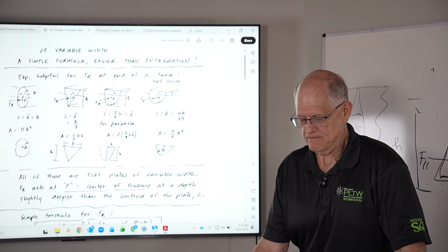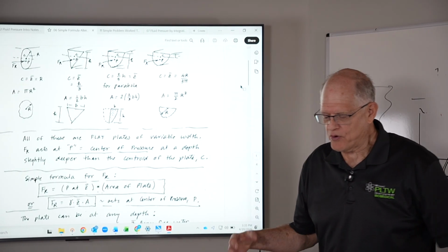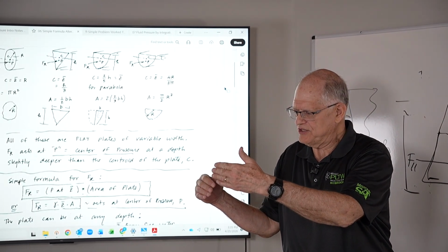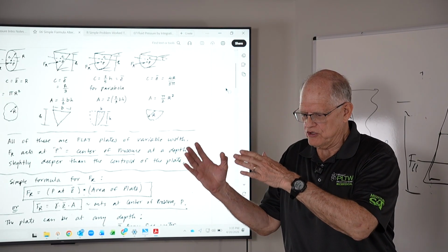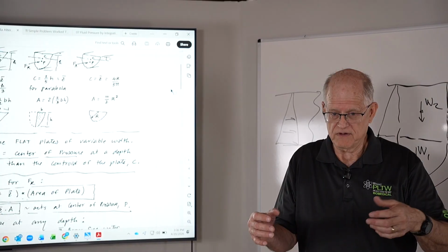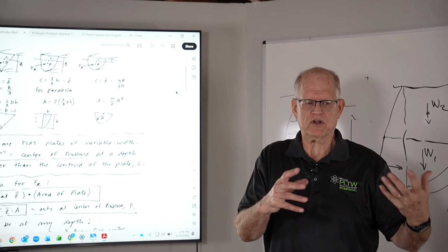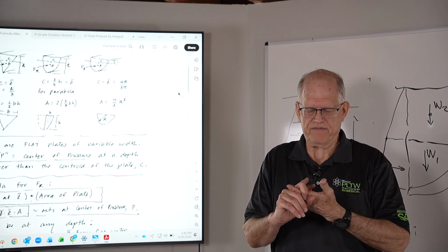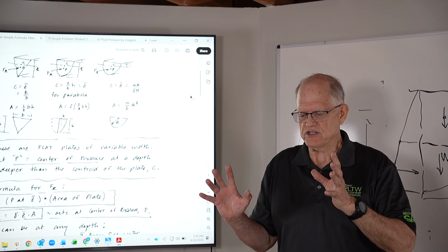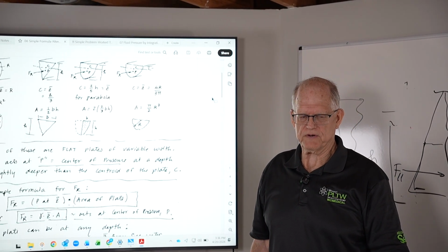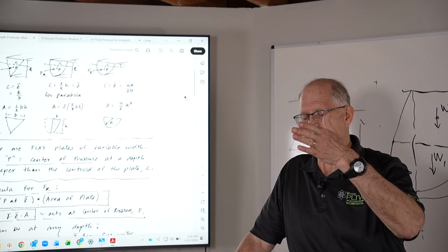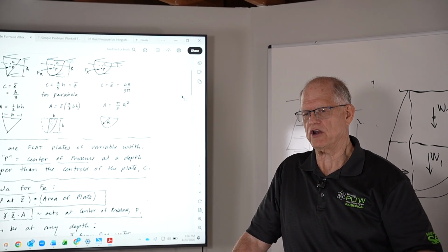Those are basically the principles of fluid pressure. We looked at flat plate, constant width problems. We've looked at curved surfaces. We've looked at integration, the general case. And we've looked at the simple FR is equal to gamma z bar area. These are principles that you can use for fluid pressure. Anyway, questions on that? And again, fluid pressure exerts a distributed load on a surface.